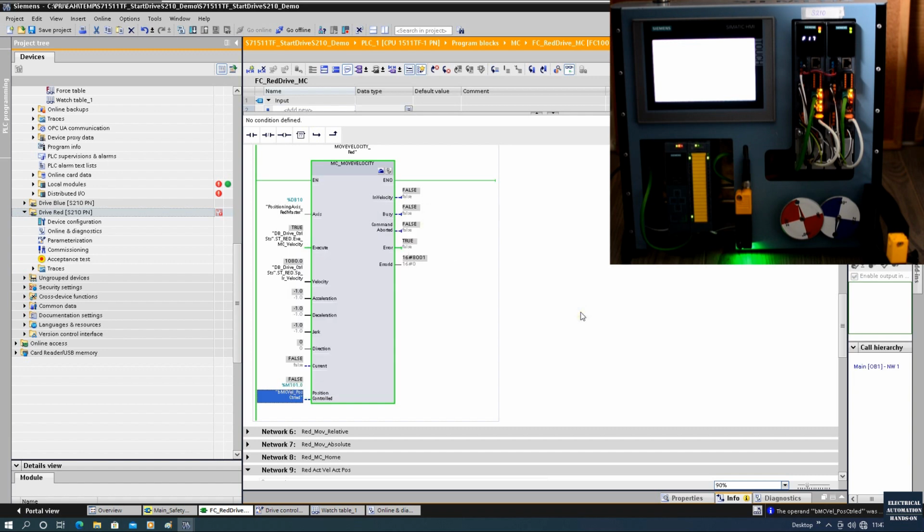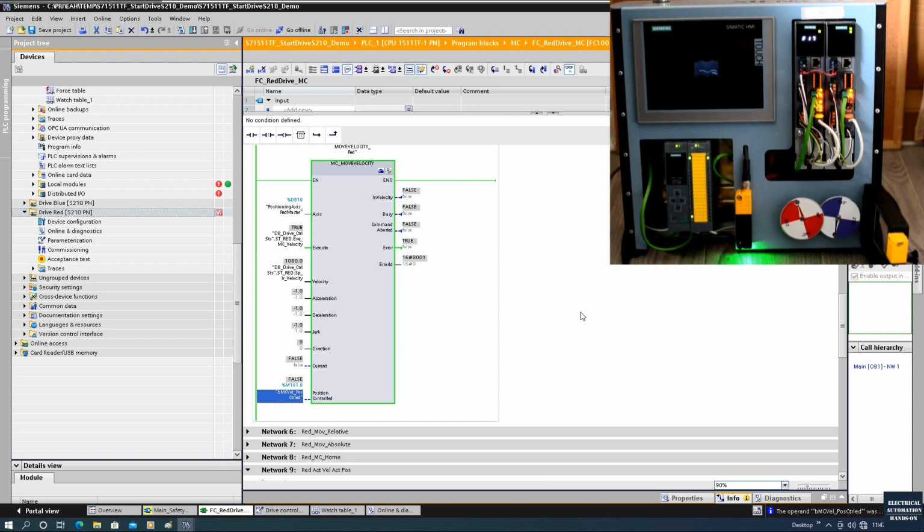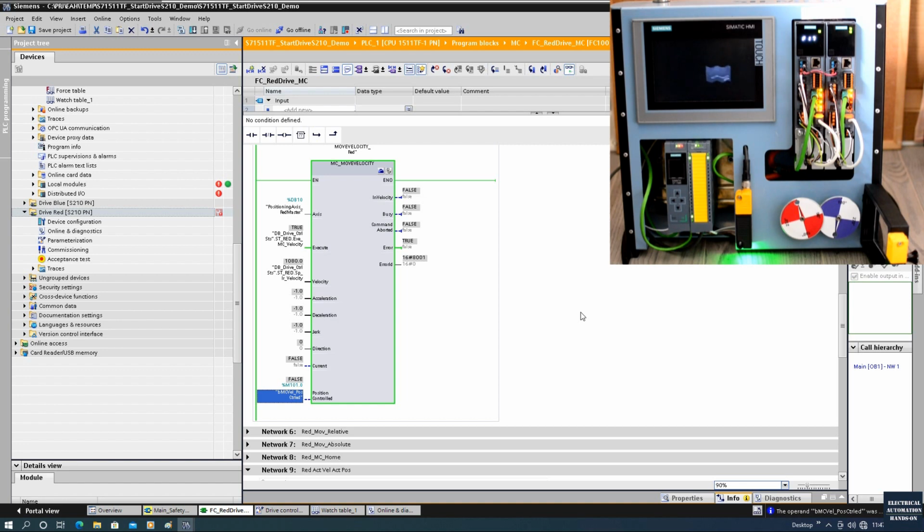That's because while blocking the motor, the internal positioning loop is still running. Once I release, the feedback and the set point have a huge difference. Then the system will feel very confused and try to catch this set point. But while it's catching, the speed may be too fast, acceleration too fast, and then the motor or the mechanical things will not feel happy. So this is the thing you really need to prevent. So while using the TorqueRange or TorqueLimit, take care, we need to turn off the move velocity.